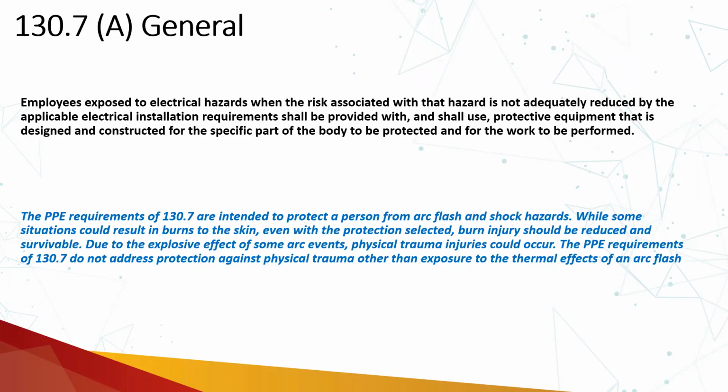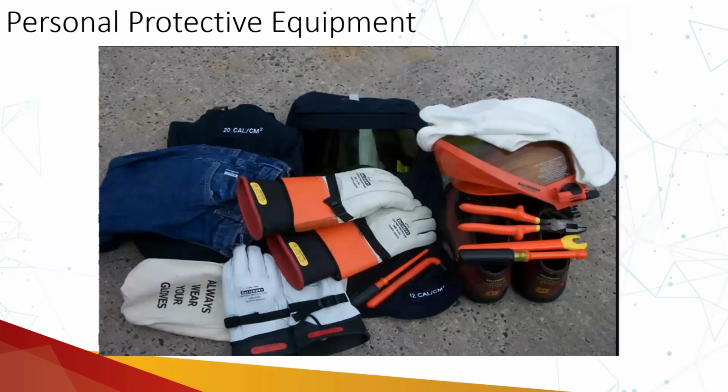So those are the generic personal protective equipment covered here, which include protection against shock hazard: rubber insulating gloves, leather insulating gloves, or rubber insulating gloves and leather protectors in combination, which will provide you protection against both arc flash and shock.